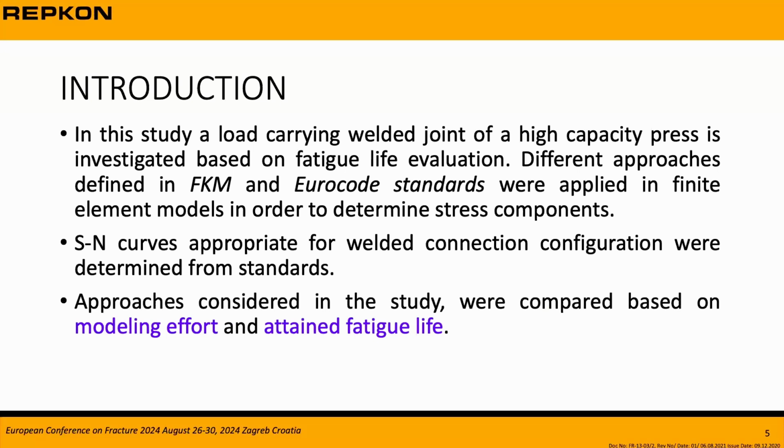In this study, a load-carrying welded joint of a high-capacity press is investigated based on fatigue life evaluation. Different approaches defined in the IIW and Eurocode standards were applied in finite element models in order to determine stress components. S-N curves appropriate for the welded connection configuration were determined from standards. Approaches considered in this study were compared based on modeling effort and attained fatigue life.